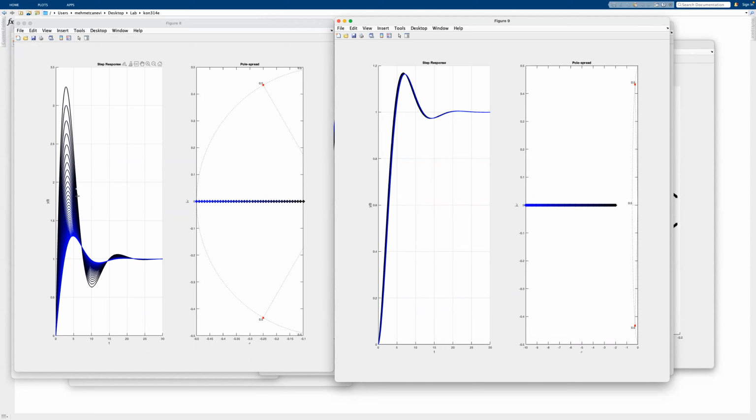But here we can see that's not the case. Here we have like 350% overshoot, something like that. So it is way worse than adding a pole to the system. So if we have a 0, then we might end up in a very bad system response, and also even higher overshoot values and all that stuff, which is not nice at all.